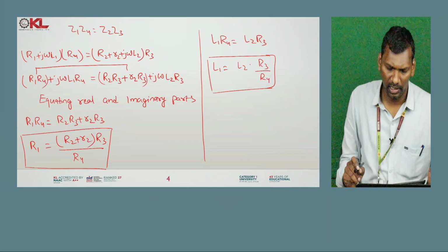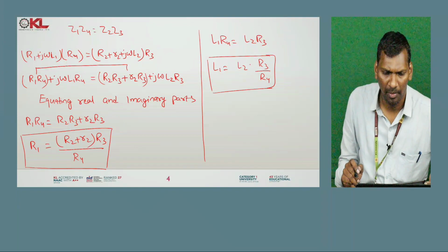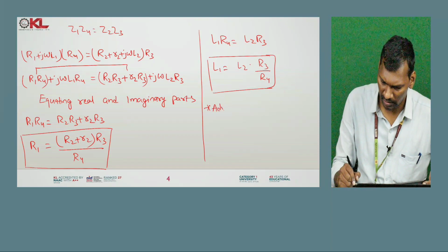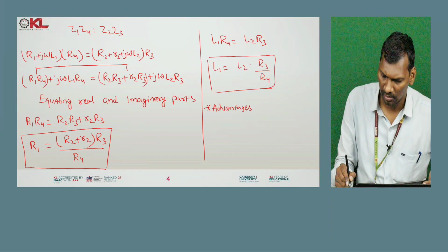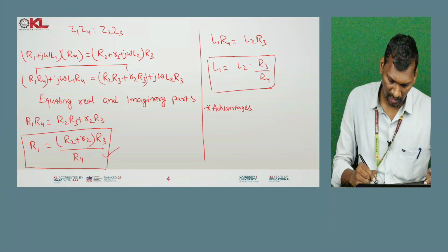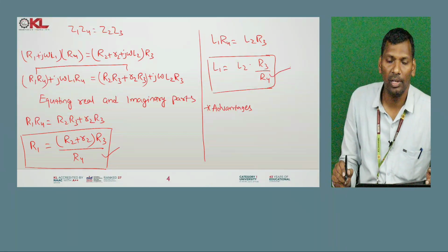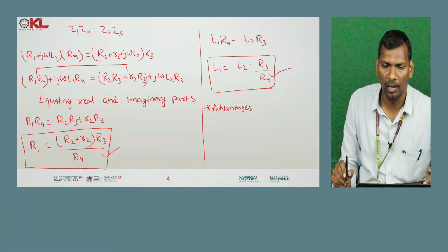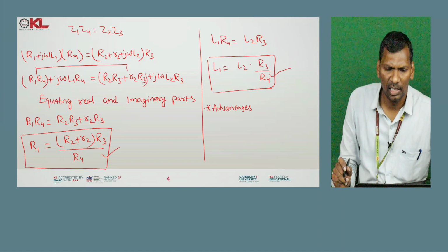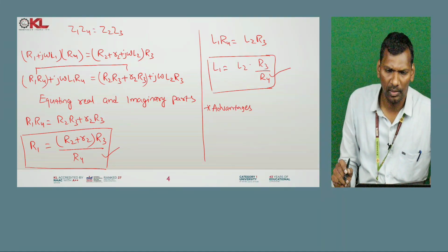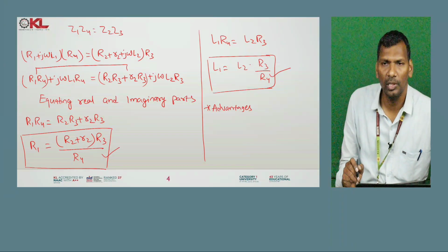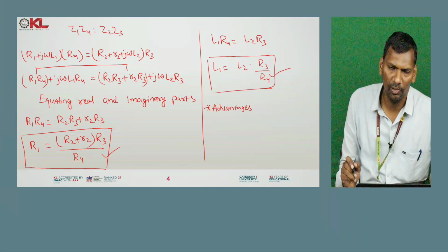But what are the advantages and disadvantages of the Maxwell's bridge? So, first let us consider the advantages. Here the expressions for calculating R1 and L1 are very simple, and these two equations do not depend upon the frequency, and R1 and L1 are independent of each other. These are the advantages.